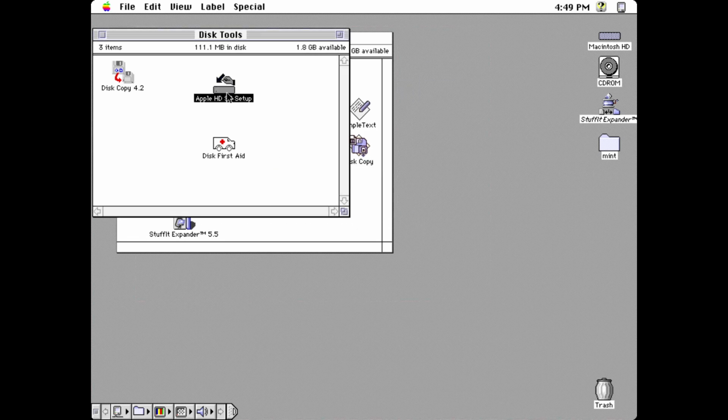But this is because with the original SCSI hard disk from Apple, people think it's only about the model name and the manufacturer name on the drive, but it's not. The SCSI hard disk from Apple has a specific mode page, the same for the SCSI CDs, that tells them this is an Apple drive, so work with me.